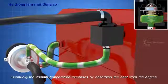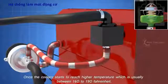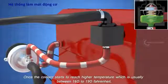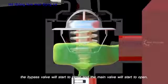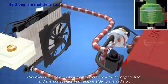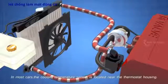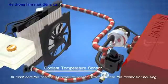Eventually, the coolant temperature increases by absorbing the heat from the engine. Once the coolant starts to reach higher temperature, which is usually between 160 to 190 Fahrenheit, the bypass valve will start to close, and the main valve will start to open. This allows the cold coolant from the radiator to flow to the engine side, and the hot coolant from the engine side to flow to the radiator. In most cars, the coolant temperature sensor is located near the thermostat housing.